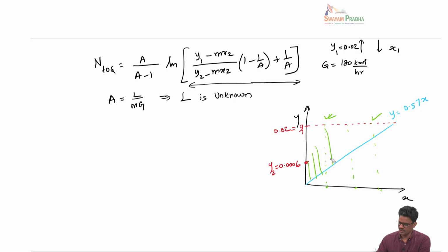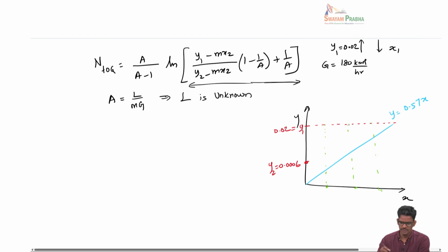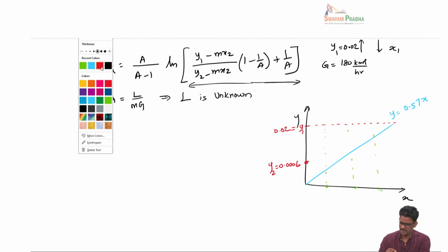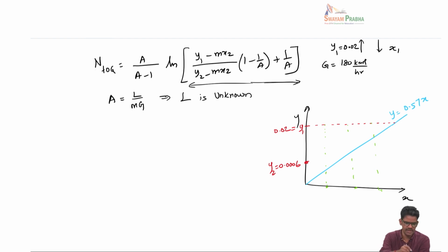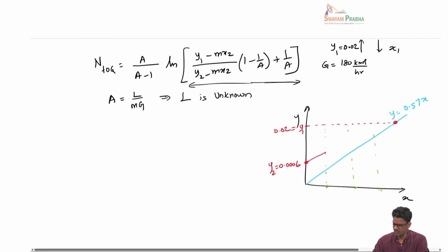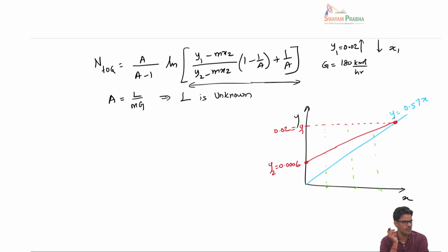So I'll just delete all this. So the minimum would be something like, the minimum is one where the outgoing liquid is in equilibrium with the incoming gas. Okay, and we can calculate this. I know all the information. So this would be the slope corresponding to LS minimum.